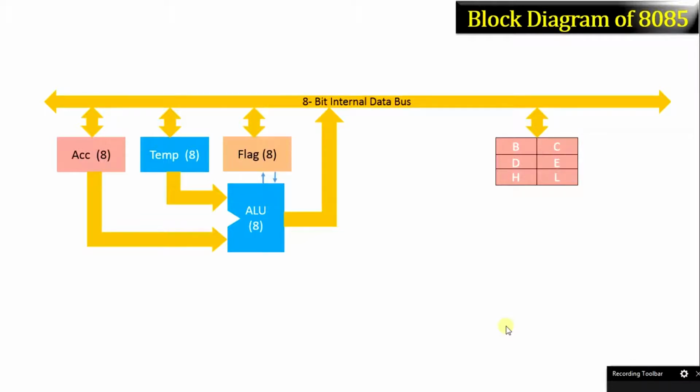So in the memory we will store instructions or the program. Whenever these programs are stored in the memory, this circuit should tell the address of that memory, so that the instruction stored at a particular address can be read or fetched by this IC, and then it should decode it, and after decoding, it should perform according to the instruction or program, isn't it? So what type of modification do we need here?